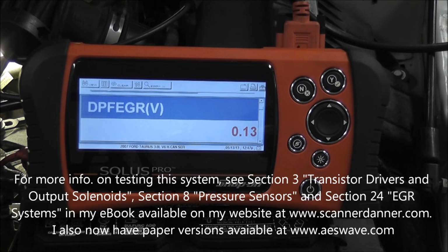Right away, it's not reacting like it should, and I know some of you are thinking, put a DPFE sensor in it already, right? And I would agree with you, it's a Ford. All of these DPFE sensors go bad. We're going to check it anyway. I think the stuff that we covered is going to be valuable information for other Fords. And then also, we're going to do wiring checks to this DPFE to make sure that they're correct and we don't have an issue with the reference wire, the ground wire, and we can be 100% confident on this sensor.